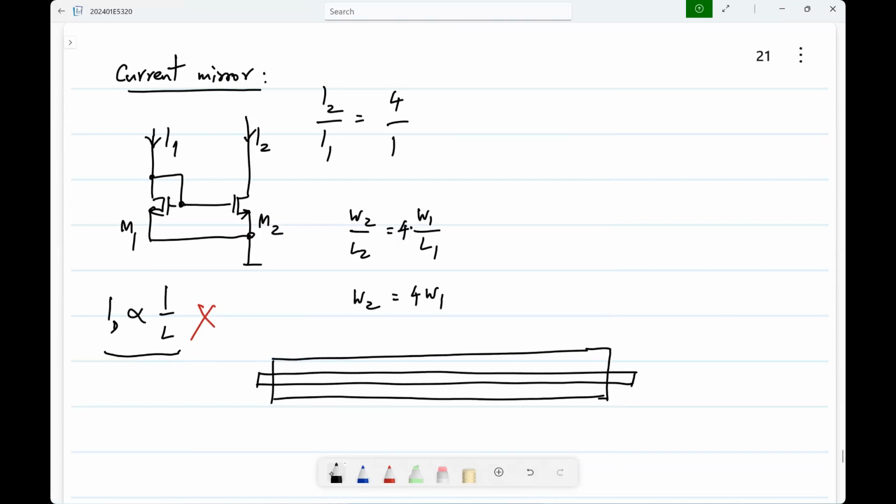So you have heard of terms like, for processes, something like, let's say, 65 nanometer process or 16 nanometer process and so on, or maybe 5 nanometer process now. Okay. What is all this stuff? What parameter is it? It's basically some minimum dimension that can be fabricated in that process. Usually it used to be the minimum gate length.